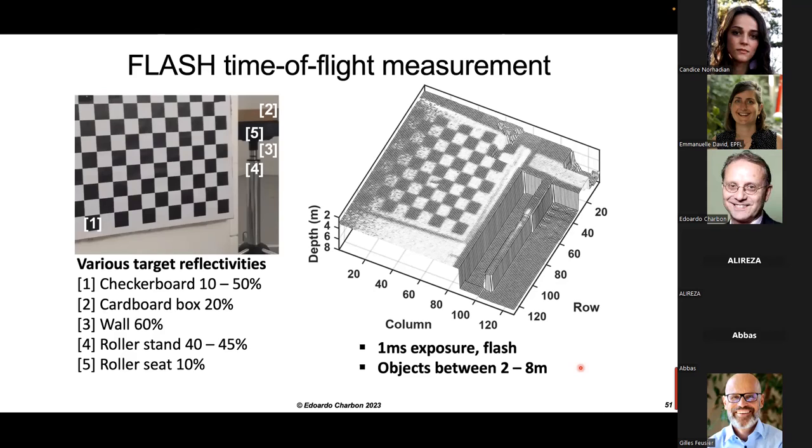There are new techniques that just came out, like the White Rabbit, for example, which has been around for just a few years, which are protocols that could be applied to achieve synchronization levels of the order of a few picoseconds, even in low-cost, low-power devices at variable distances using fibers, or perhaps even using radio frequency.